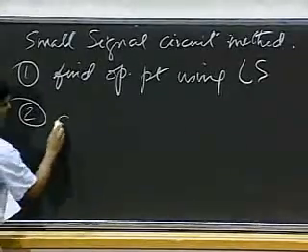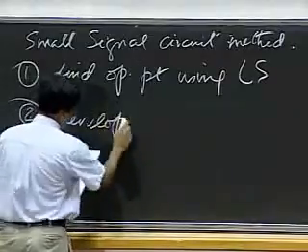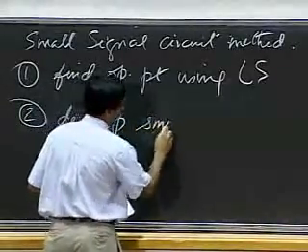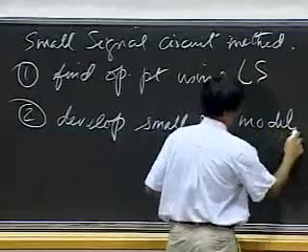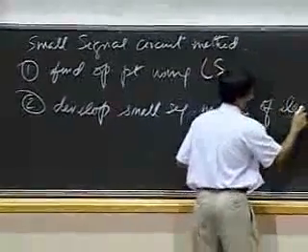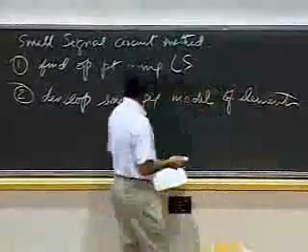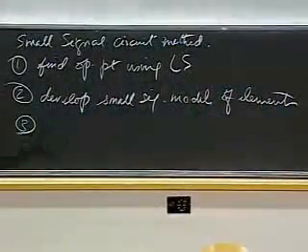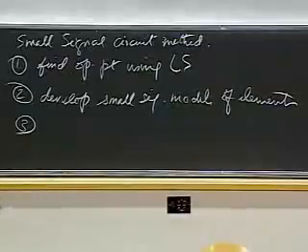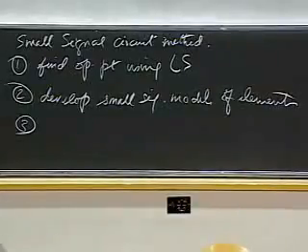The second step is to develop small signal models: take each of the elements in your circuit and find their equivalent small signal circuit model.